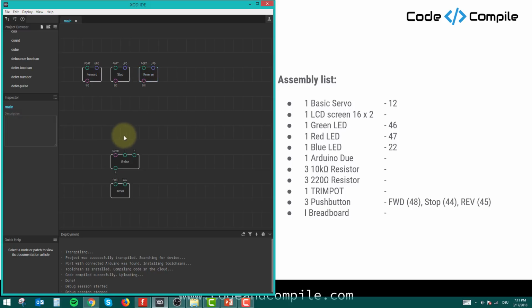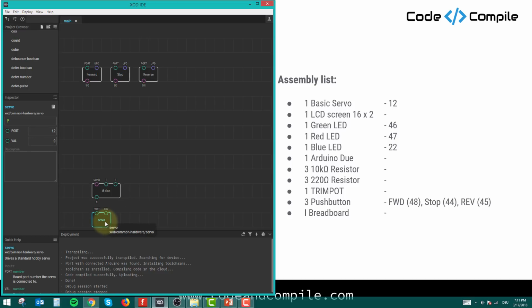Very nice. Now, you know we have three values which we need to move in the servo. My servo rotates clockwise when I move 1 in that. It rotates anti-clockwise when I move 0 in that. And it just stops when I move 0.55 in that. So I need to move three values. And I need to interlock these values. So how can we do that? So for interlocking, I would prefer you to use flip-flops.